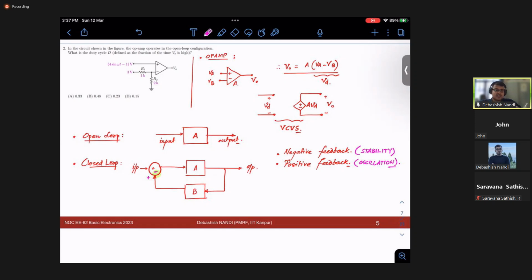But you have some inertia, so it will not always remain at 40, but you will get some higher value, maybe. Suppose you go to 45, then after looking at the speedometer, you will see that you need to reduce your speed. Then you will turn your accelerator in the opposite way and reduce your speed, and in that way you will maintain your speed at a stable velocity of 40 kmph, right? So here your eyes and your speedometer act as a negative feedback.